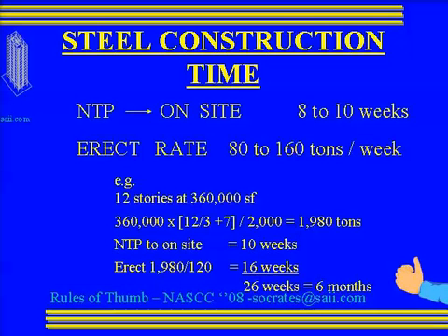Sometimes you're in a meeting and they also ask you how long before the steel is done. And you can tell this slide is outdated. We need Mike Engstrom in here to tell us what the real delivery time is, but it's not 8 to 10 weeks anymore from the notice to proceed. It's more like 14 or 20. Depends whether you buy your steel from a service center or from the mill.